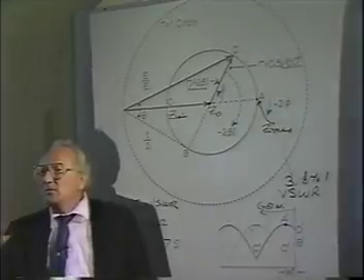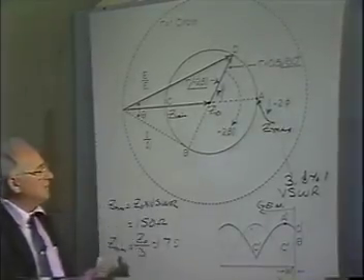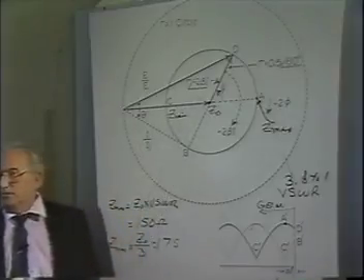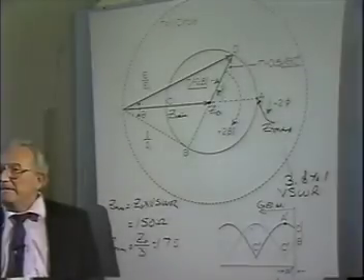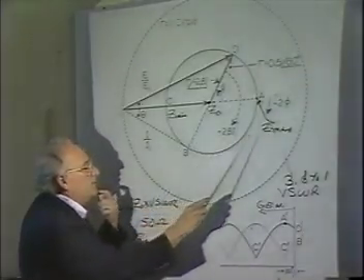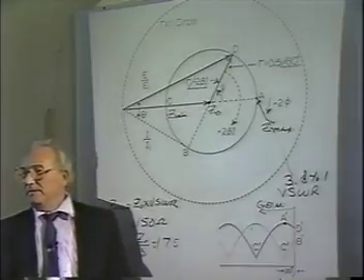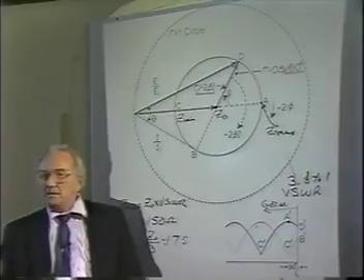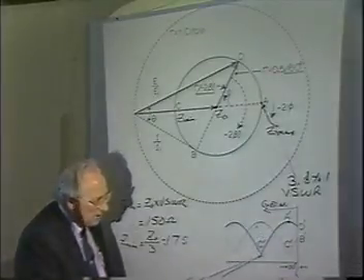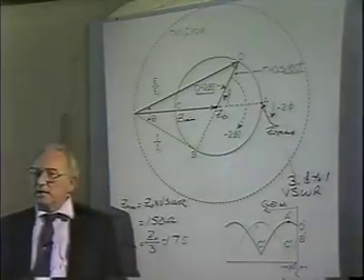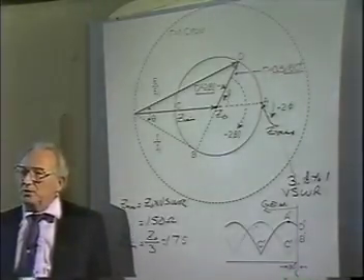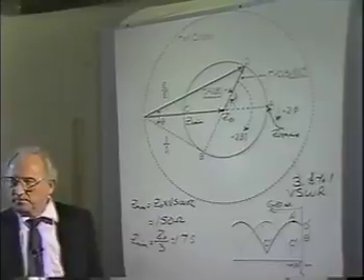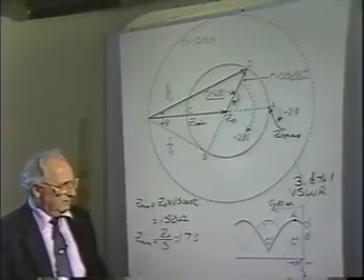Pure resistance. Anywhere along this line, 0 ohms, 5, 10, 15, 20, 25, 30, up to 50 ohms, if this is a coaxial line, starting at 50 ohms, up to infinity on the other side. That's the impedance relationship, but that's the pure resistance axis. At no other time do you have pure resistance on that line unless the line is perfectly, absolutely matched. Then, as far as you're concerned, it's pure resistance all along the line. Any problem with this?